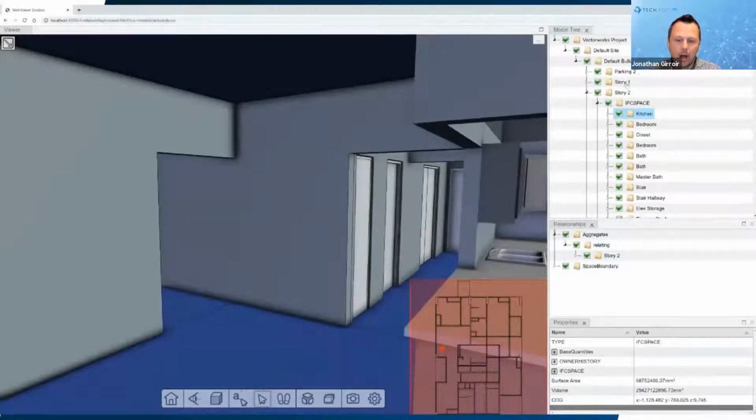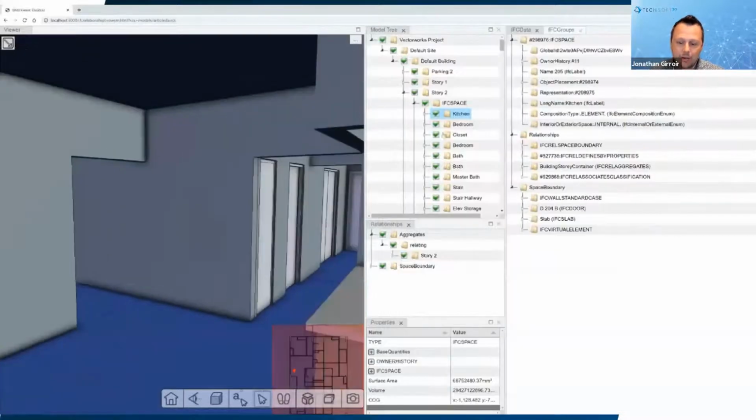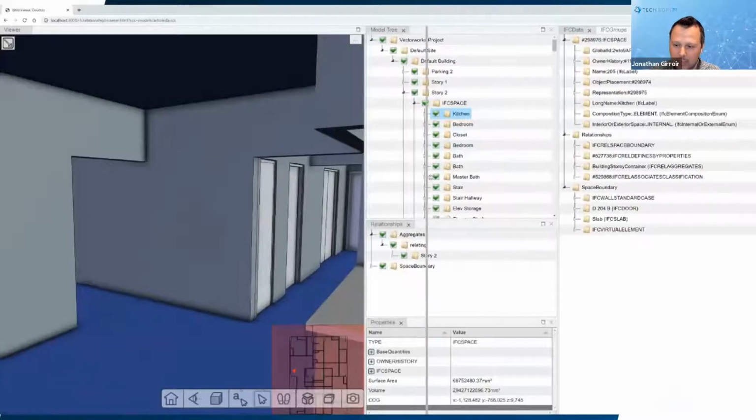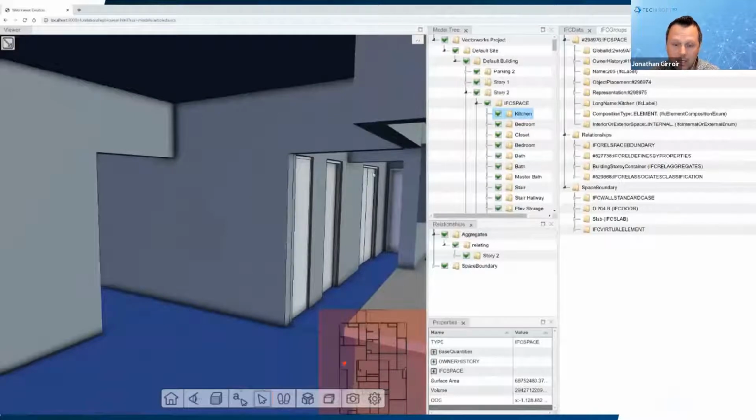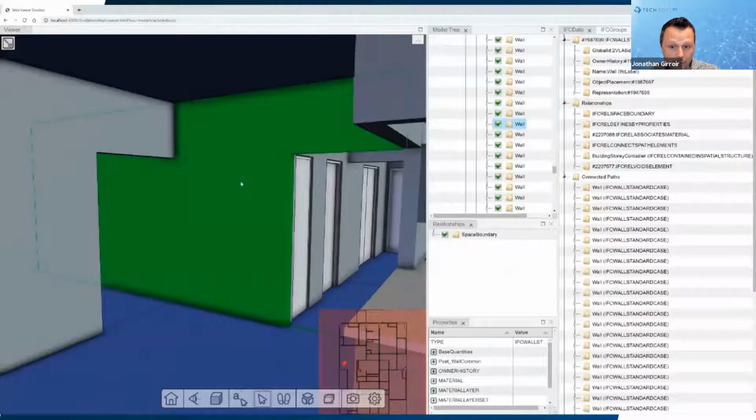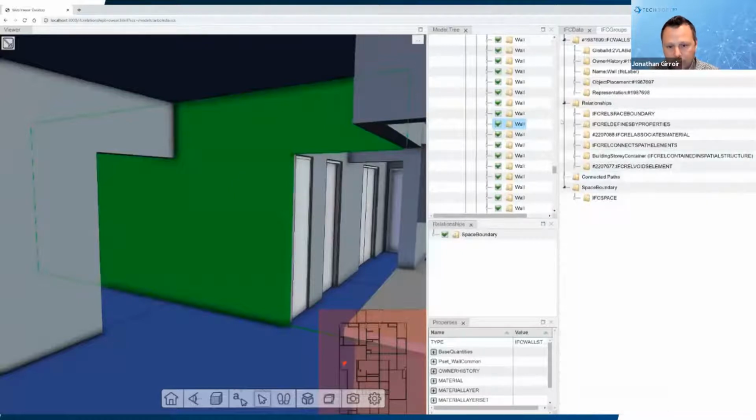And so our CAD data access toolkit is called Hoops Exchange, and it can generate an XML file that contains all of that relationship data. Some of it we're showing here. This is a demo, so we built an additional small UI here on the side to start navigating that XML data. What's pretty common is you get all that additional data, and you may have your own as well. So to augment this as well, you put it in a database. We've done that here. So we took the XML data, put it in a database, and now we're querying that on the server, and we're looking for different relationships.